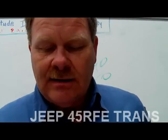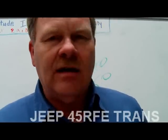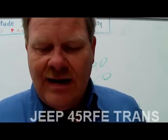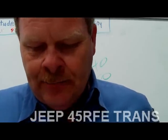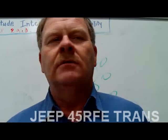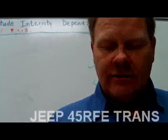The input speed sensor reads input shaft speed off a tone wheel. There's nothing mysterious about that. We've all seen that plenty. And it compares that reading with that of the output speed sensor. So you've got basically input shaft speed, which is what else we call the input shaft? What's the other name for the input shaft in the transmission? Turbine shaft. Good answer.